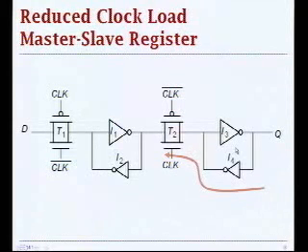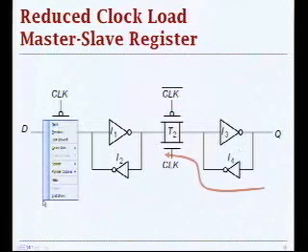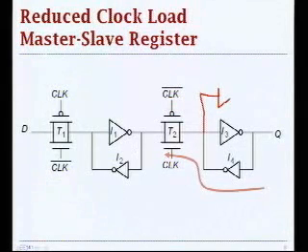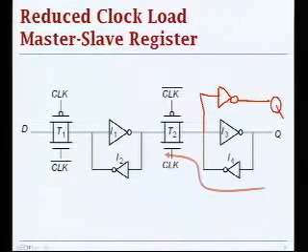There are also ideas in the implementation that people use, for example, you want to isolate your output, and the idea is to add a redundant inverter over here, and take the output of that instead of here, so that you can downsize this one and keep all your internal nodes protected, and then drive the large fan-out capacitance with this, right? Because if you have a large fan-out capacitance, you don't necessarily want that to load the input of this small gate. So that's one of the ideas that's commonly implemented in practice.